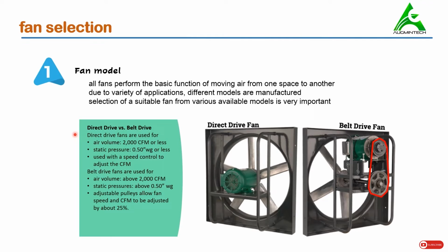They can be having different sizes which will regulate the speed of the fan, and CFM can also be adjusted by a factor of 25%. Now wherever high temperature fans are required to move air above 50 degrees centigrade or 122 degrees Fahrenheit, belt drive fans are always recommended.